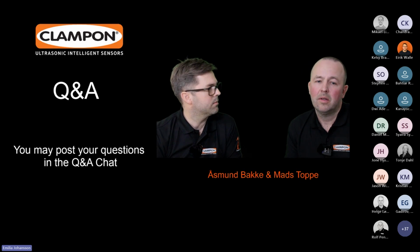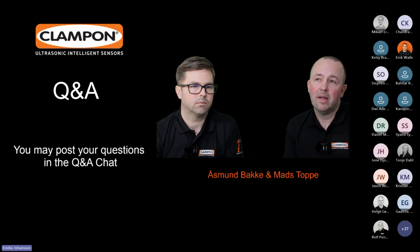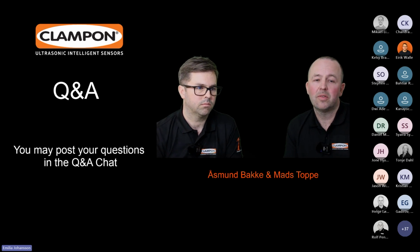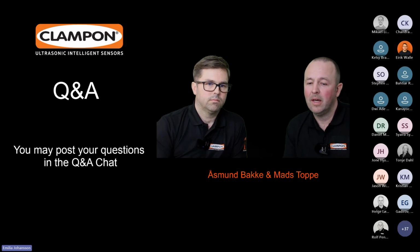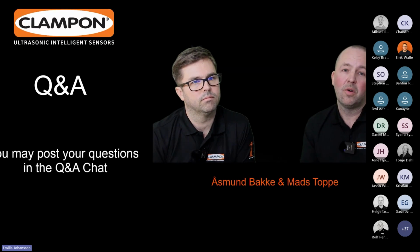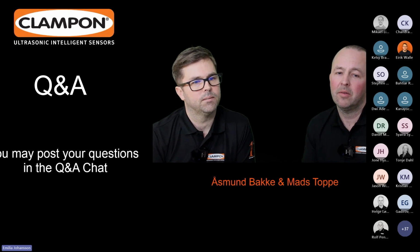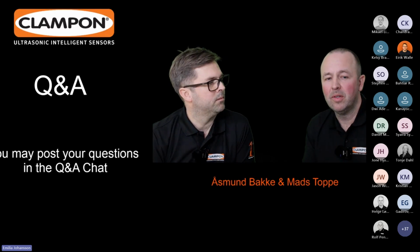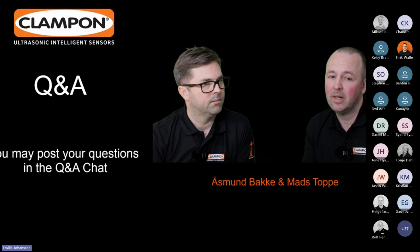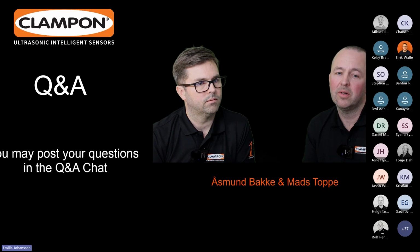When we collaborated on the sand flux work, that investigated ways of finding a way to calibrate systems where you can't do sand injections. We combined that with a whole reanalysis of all our own historical sand injections, and we saw that we could improve the default tables a lot by including the typical grain size and the gas-liquid ratio in those.